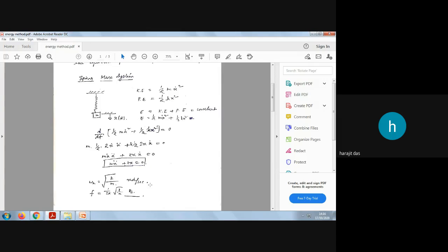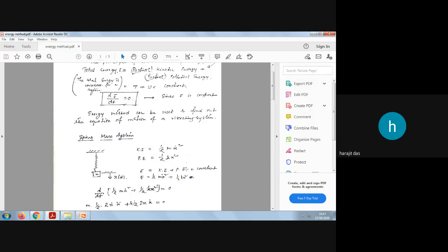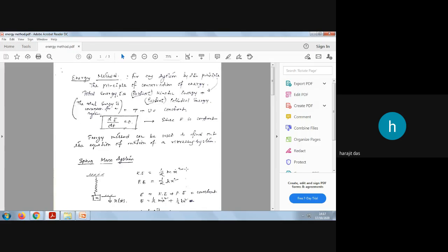Okay, so this is the same expression as we have found earlier. Then linear frequency will be f equals 1 over 2 pi root over k by m hertz. So in both expressions, you need to finally find out the natural frequency for any derivation, because in a numerical problem both things may be asked, or sometimes linear frequency may also be asked. Understood? I think this is very easy, so no need to repeat it again.